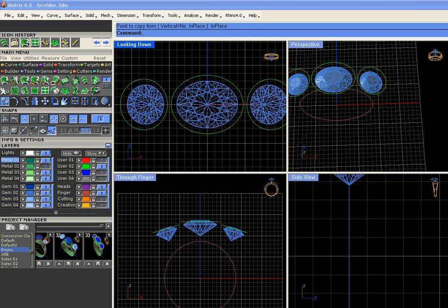Now essentially we want to split these so we can blend them, and we kind of have the same issue. We need to split them judiciously. So let's run the split command with a point. Split it twice. We're going to mirror this, so don't worry about the other side. Same thing over here. Remember, we saved off a copy of this, so we've got a record of what we've done. And blend between the two.